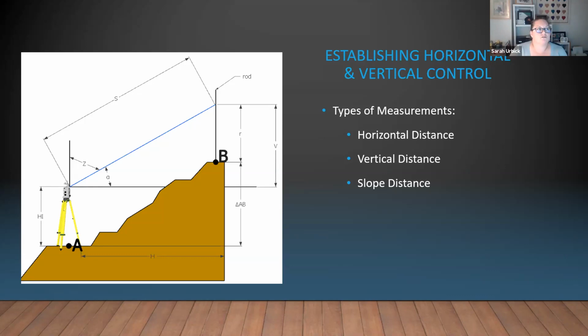One of the things that drove this concept home for me was the idea that we have to treat those slopes by the square foot. If I am looking straight down at that slope from up above, maybe with a drone with a camera, it's easy. I can measure off a quick distance between those 2 points. But if I've got a steep enough slope, then I've got a lot more surface area that I'm really dealing with, over the length of the distance between those 2 overpasses.